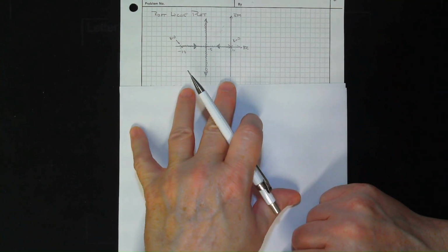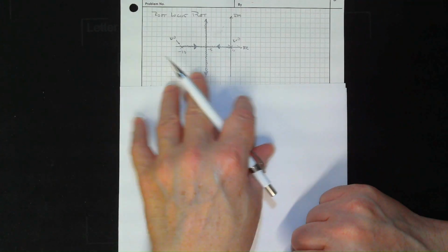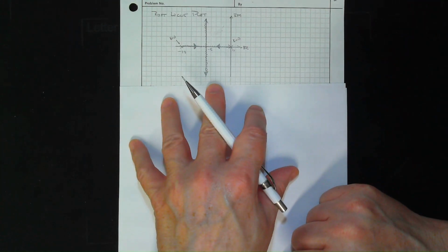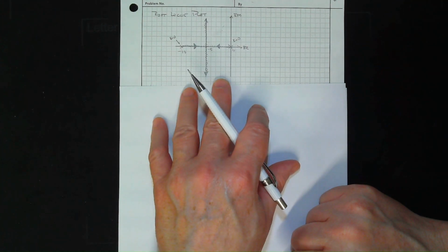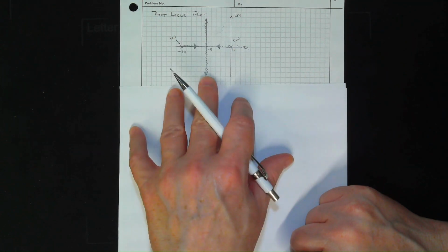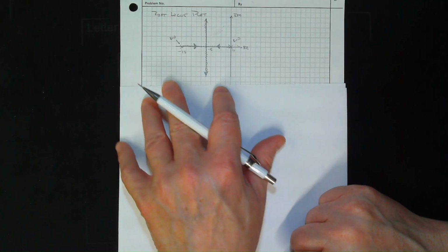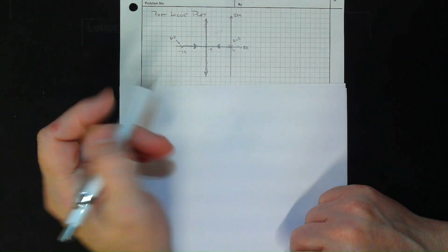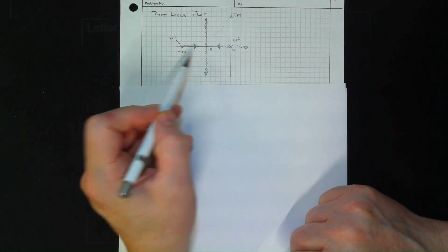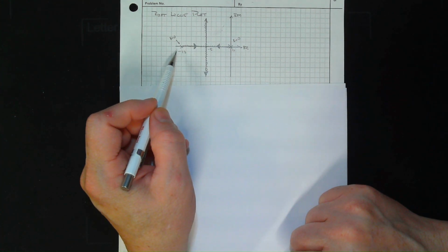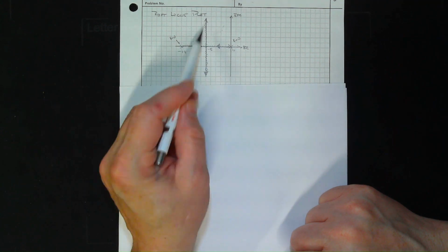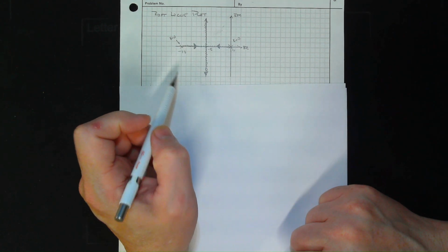From a control point of view, now by the way, we have a name for this plot. You'll learn when you go to a controls course, they'll spend a bit of time on this and teach you how to make these things really easily. But this is called a root locus plot. As you change one variable, you see where the poles of the system move. This is really useful information, okay?